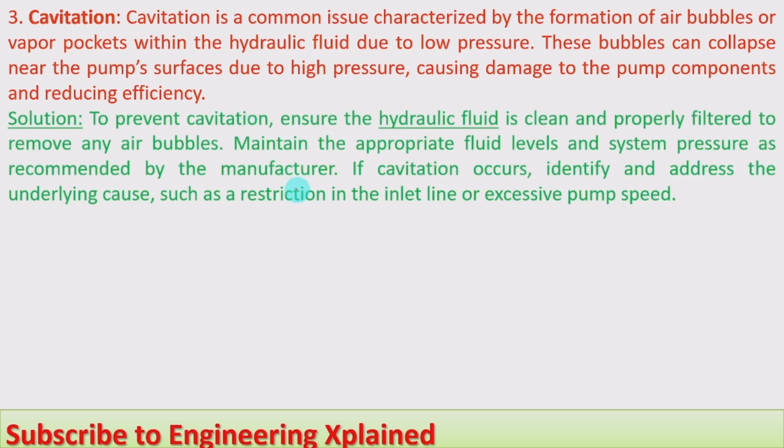For that, what solution should we have? To prevent cavitation, ensure hydraulic fluid is clean and properly filtered to remove any air bubbles, and maintain the appropriate fluid levels and system pressure as recommended by the manufacturer. If cavitation occurs, identify and address the underlying cause, such as restriction in the inlet line or excessive pump speed.